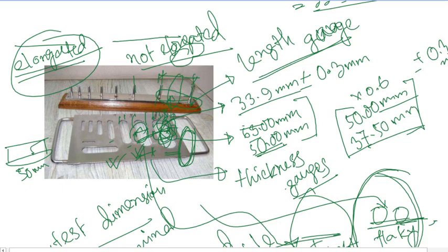63 millimeter sieve to 50 millimeter sieve, so it will be written there. Also nominal sizes will be written there, and the nominal size multiplied by 1.8 will be marked there, so you'll be able to identify. You just have to separate your particles retained on the 50 millimeter standard sieve, then try to pass them through the gauge and separate them. For elongation index also, try to pass through this. If it passes, then keep it as not elongated. If you are somehow able to restrict it, then keep it as elongated particles.